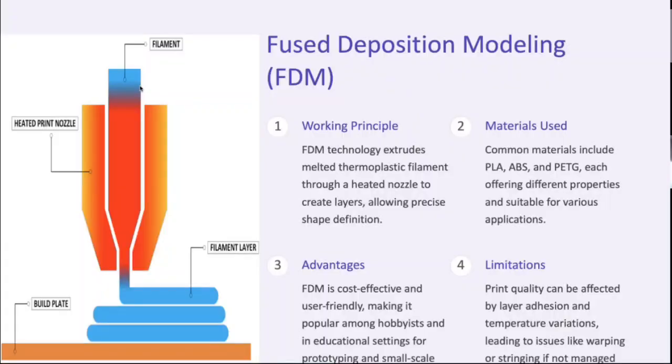Here you have the material on reels, in a string kind of form. All these strings are thermoplastics. Thermoplastics are plastics with a physical property: when heated, they turn from solid to a plastic state, having plasticity such that they can take whatever shape we want. The types of thermoplastics we use are PLA, ABS, PETG, and there are many more.